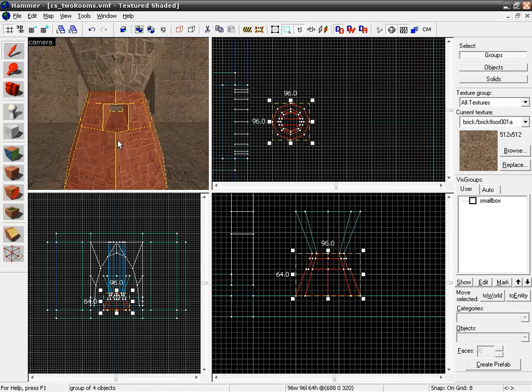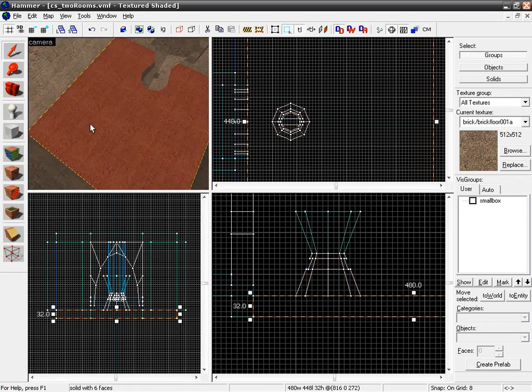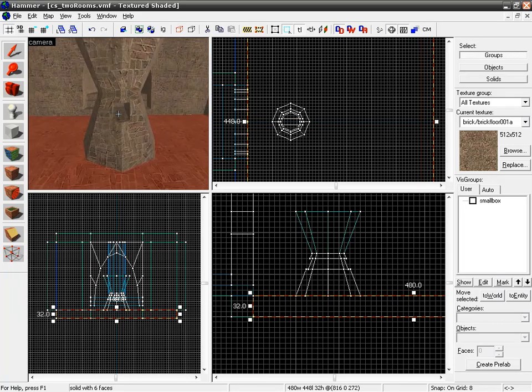But if you plan on carving anything more complex, it is a good idea to create a new, smaller shape which you can carve out of. If we wanted, for example, to carve, say, a hole in our floor, it would be a much better idea to create a new, smaller section of floor which we could carve out of, instead of carving in the middle of our floor and splitting the floor into a large number of complicated shapes. You could also use the manipulation tools to simplify the final shapes. But now that we've got our turret with shooting hole,